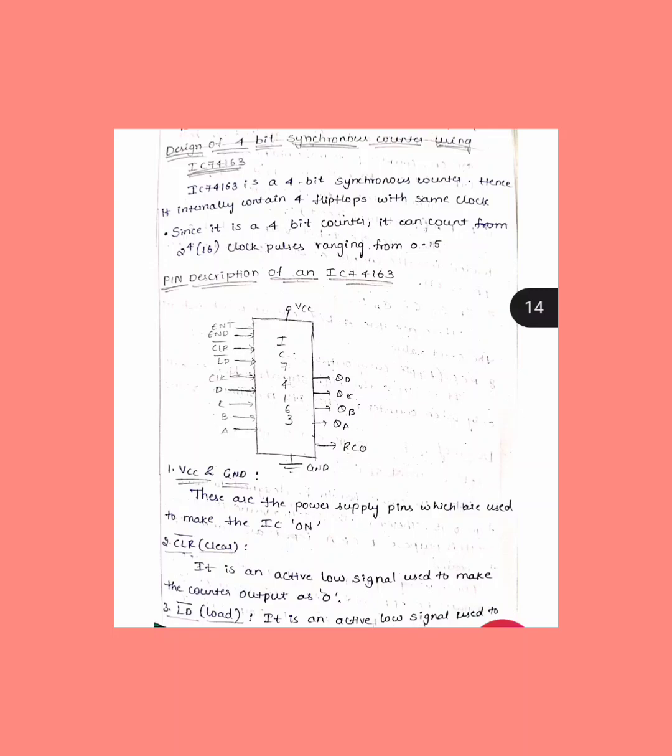Dear students, let us learn how to design a synchronous counter using ICs today. For our study, we are going to consider IC 74163, which is a 4-bit synchronous counter. Because it is a 4-bit counter, it can count 2 power 4 clock pulses. That means 2 power 4 equal to 16 clock pulses, ranging from 0 to 15. Because there are 4 bits, it requires 4 flip-flops.